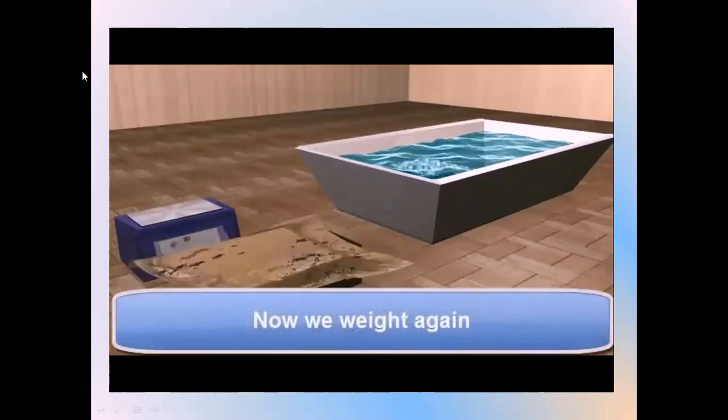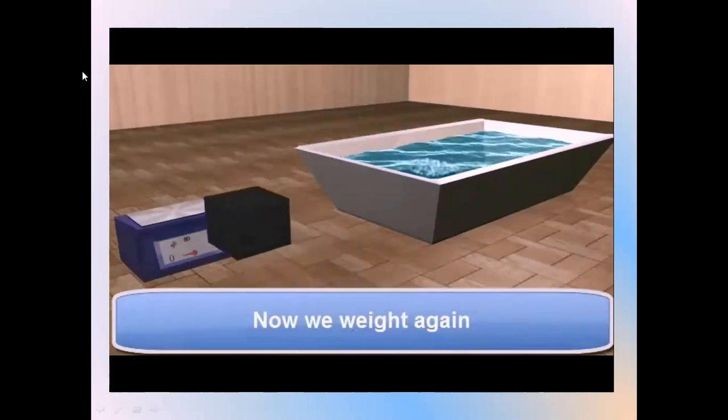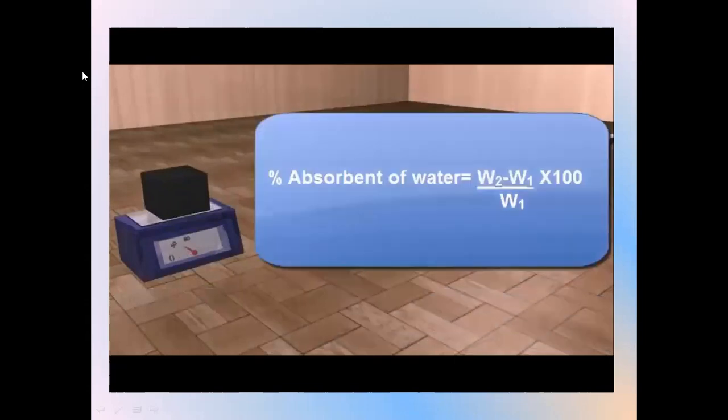Now again weigh the stone piece, called W2, and find out the water absorption. That means W1 is the dry weight of the stone before immersing in the water, and W2 is the wet weight of the sample taken out after 24 hours immersed in the water.